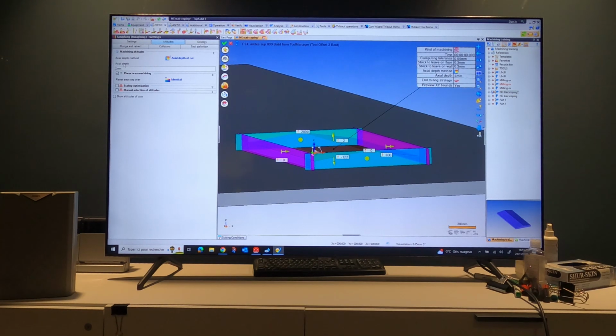At the moment you have a kind of zero calculation. You open this and put 2 millimeters. The preset for you will be 2 millimeters because this tool is supposed to remove 2 millimeters at a time. It can do 1 to 5, but 2 is a good number. It's a good value because this is correct also for granite and so on.